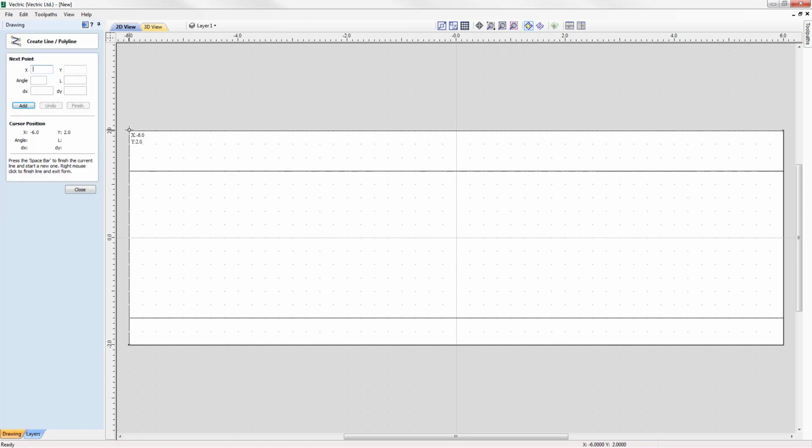So we're going to start in the top left hand corner here. You can see I'm snapping to that corner, and I'm going to drag that out by 1/4 of an inch. You can see that my cursor is snapping to the 1/4 there on the snap grid. Click to accept that. I'm going to bring that all the way down, snap to the bottom there, click to accept that, and then back to the lower left hand corner, click to accept that.